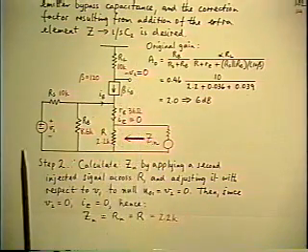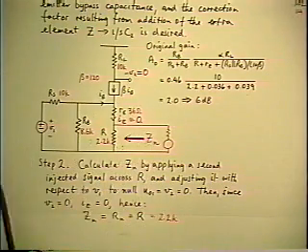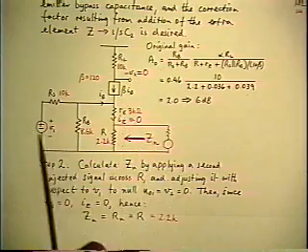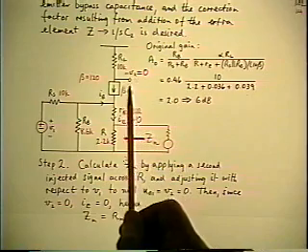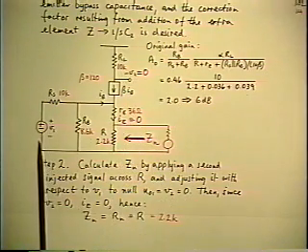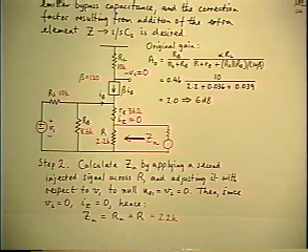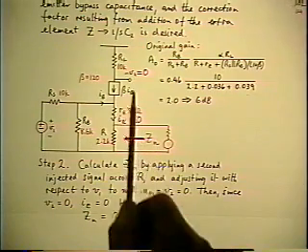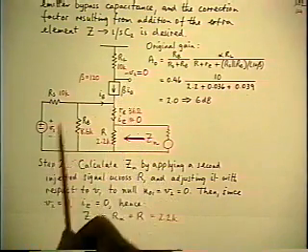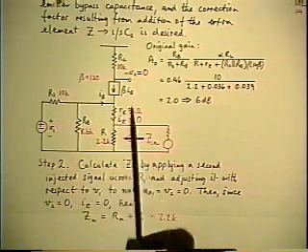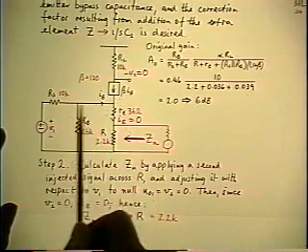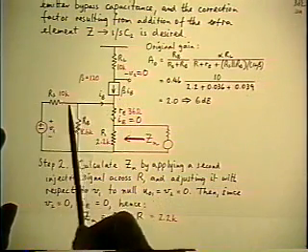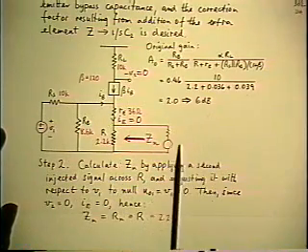That's what took the place of the knowledge of V1, because there's a unique relationship between V1 and the second source that produces the null. So if you know a null exists, this is the same thing as knowing what V1 is. You don't need both. It's the same information. So, in fact, all that you've used to calculate Zn is the fact that the null exists, and you don't need to know the V1 that caused it. That's why the argument simply followed the null back to the second source, and you never had to know what went out here. Now, if you want to know what goes on out there, you can find out.